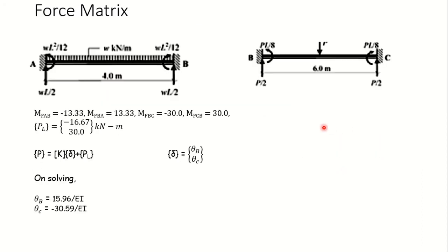Okay, now calculation of nodal forces. Are there any forces which are directly applied in the coordinates? No, we don't have any such forces directly acting in the coordinates of the beam. So that P matrix will be 0. Whereas the forces which arise in the coordinates due to the loads applied over the member, they exist.